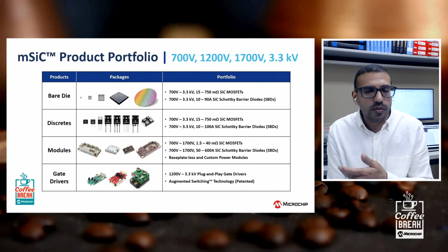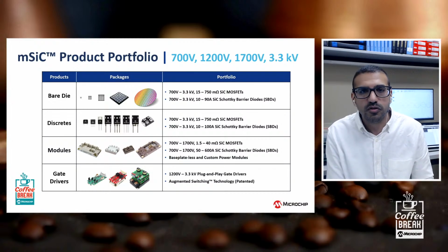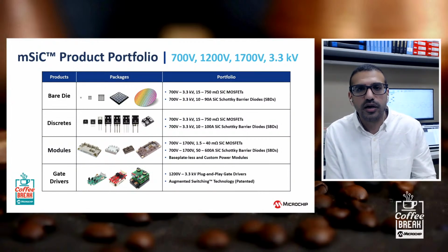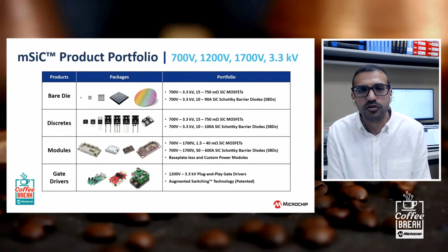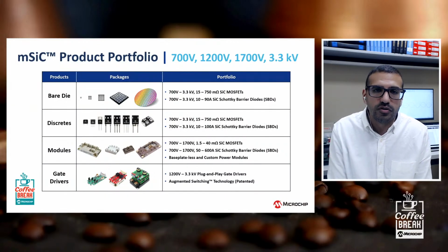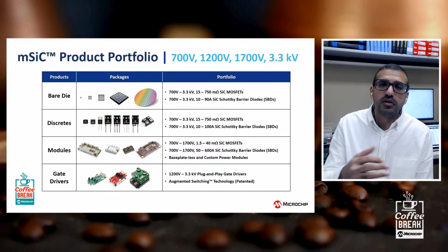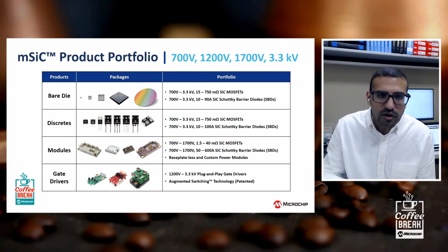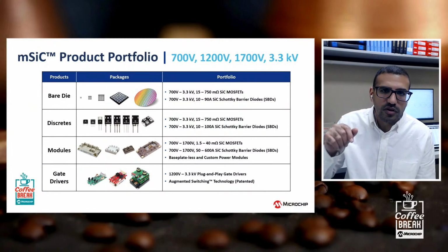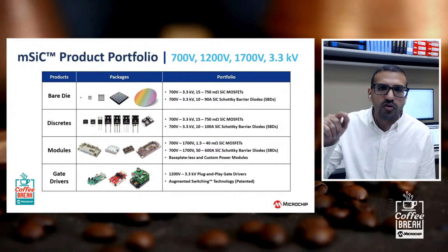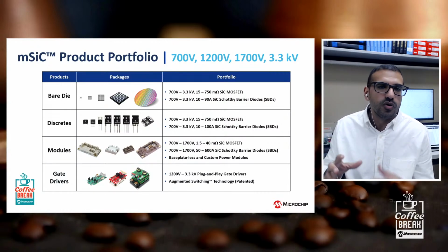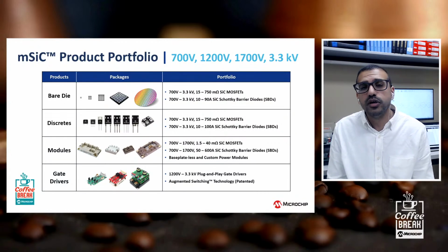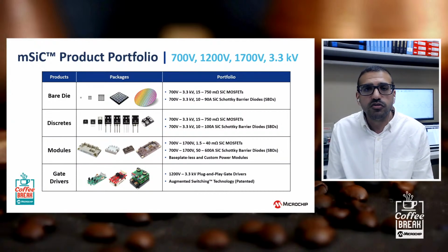So we have a broad portfolio of silicon carbide solutions. You can see we have die, discrete, and modules, and we have gate drivers. And we work with customers to ensure that their designs are driving the silicon carbide MOSFETs properly, that their circuit is designed properly, and that the overshoot that occurs at turn-off is managed so that it's not so high and you don't have so much ringing.